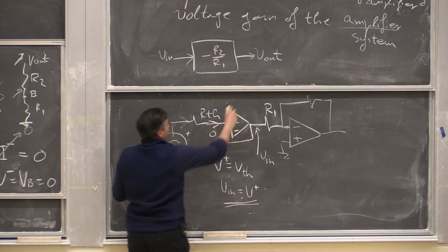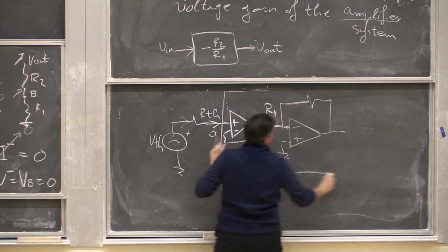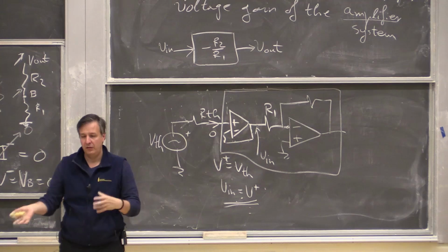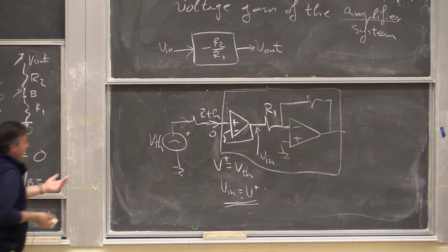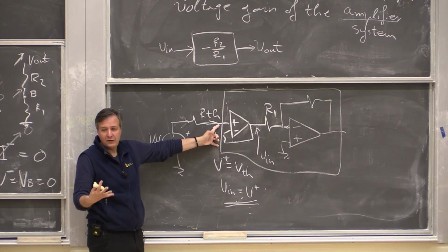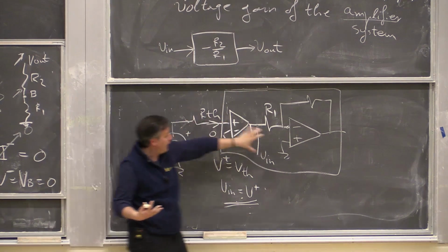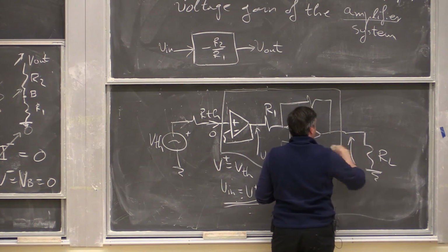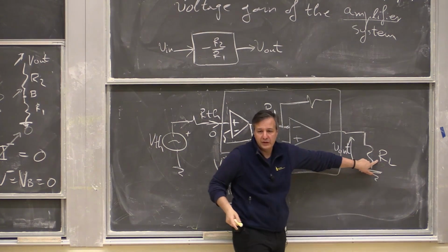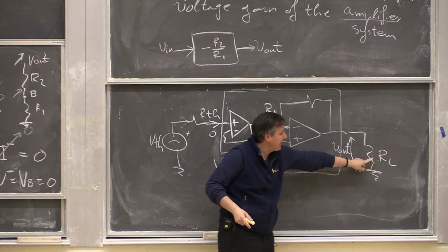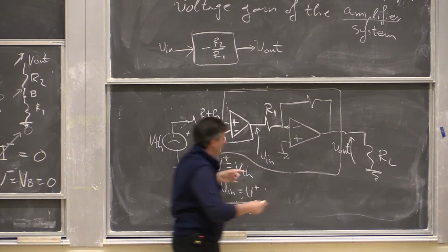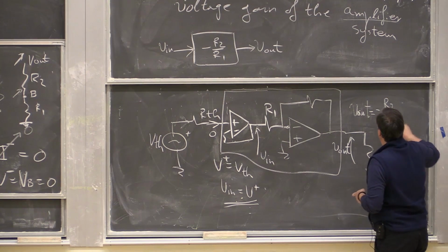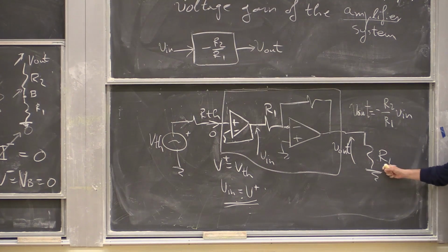So this now, if I now make this my block, then I can take this block and attach it, put it anywhere in the circuit. And it will just sense the voltage without disrupting this previous circuit. And it will produce V out regardless of what the load is. So can anyone tell me why can it produce a given V out? V out here will be always minus R2 over R1 V in, regardless of R load. Why is that the case?